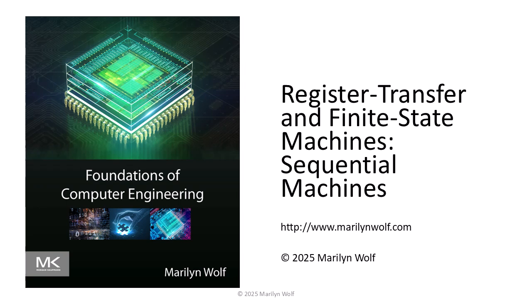A sequential machine uses registers to manage when combinational logic values change. The outputs of the sequential machine depend on both the primary inputs of the machine and the values of its registers. To be sure the sequential machine works properly, we manage the structure of the machine, the timing of signals into the registers, and the properties of the clock.